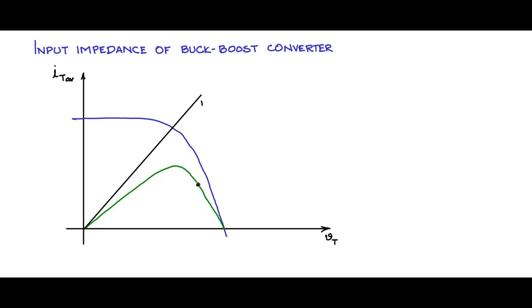In green you have the power versus V curve, and I have a load line here, 1 by RT, and at the point of the intersection we have this operating point, and when you drop it down, it drops down to the power curve, and that is PM, the maximum power. So this is a maximum power operating point.